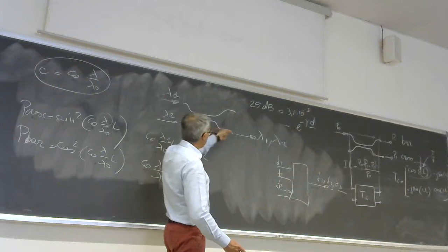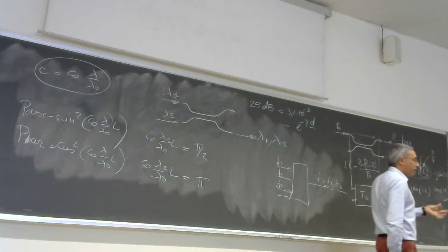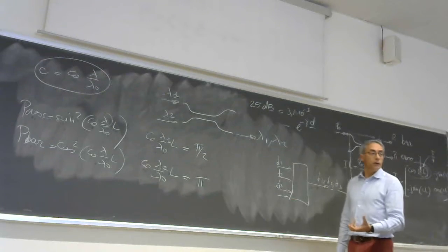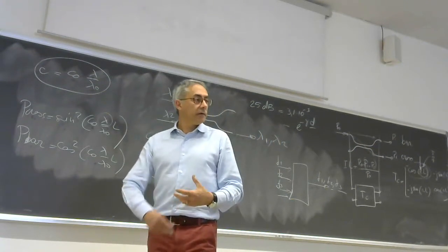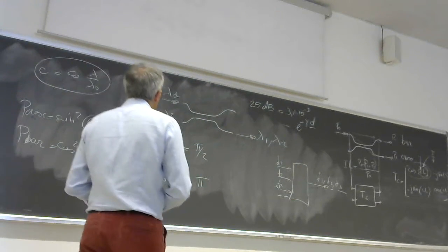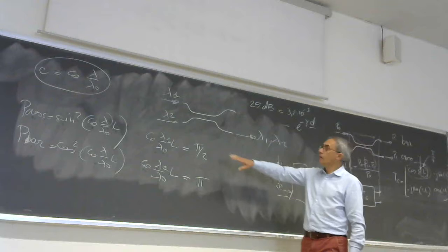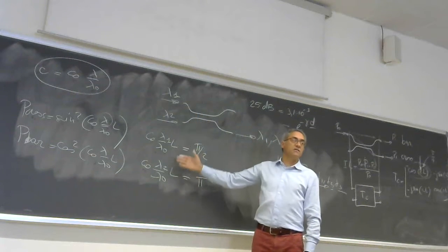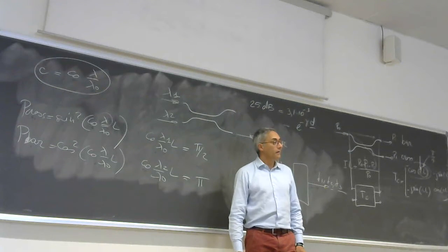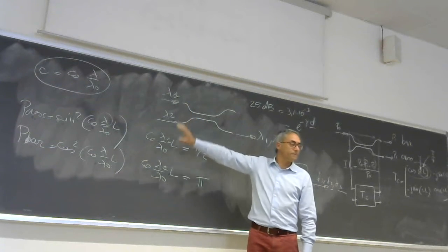So lambda 2 goes straight and arrives at this point. So this is wavelength multiplexing. You can combine the two wavelengths, exiting from the same port. And this is the basis of WDM systems. WDM systems usually have tens to hundreds of wavelengths, so we need something like this that operates on 64, 128, 256 channels. So this is more complex, but we are just starting. So be happy with two.